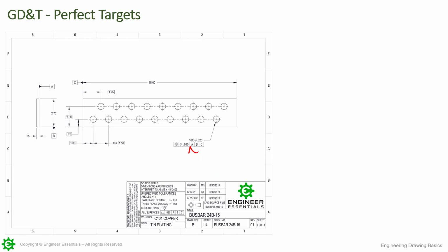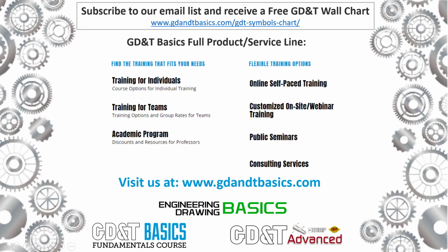So something for you to consider as you get into the fundamentals course and familiarize yourself with position tolerancing. That would be the most accurate and best way to convey it. You can go in and start opening this up a lot, the actual tolerance, and make it still functional, more functional than what the other two would allow for, but be very specific about how it gets inspected and the fact that it's coming from datums. Okay, so I hope that answered everything up for you there, Tyler.